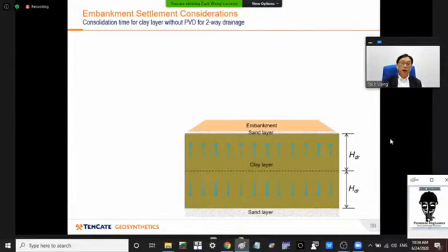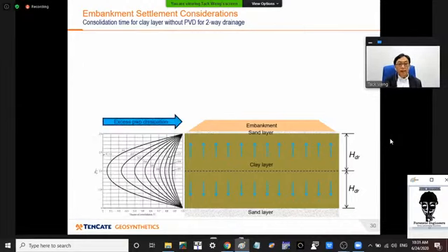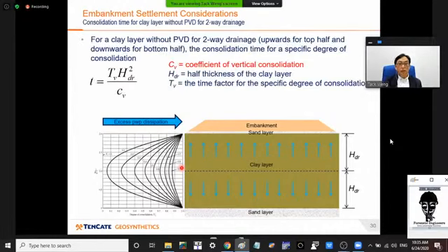It's trying to find a way to depressurize, basically. This chart here shows you initially the line of excess pore pressures, and gradually with time this will reduce down, and how quickly it reduces is very important.